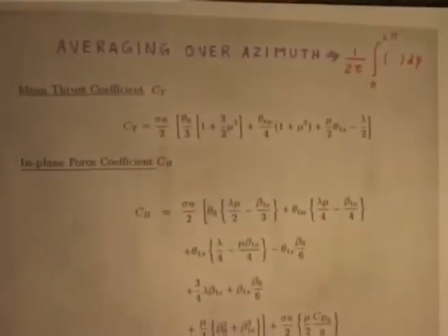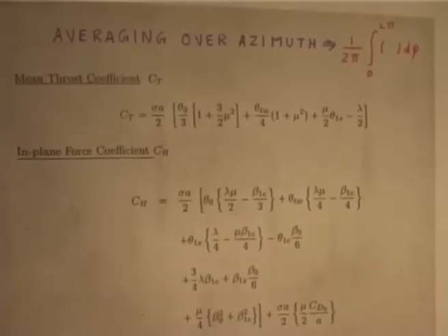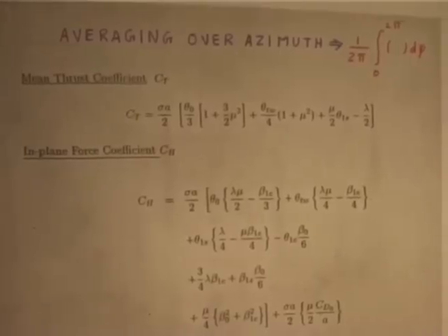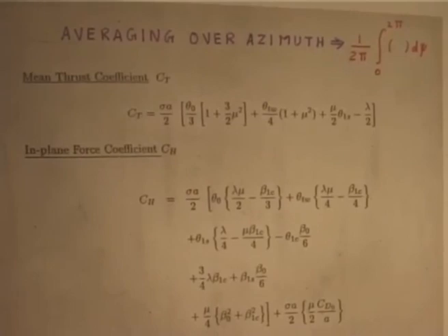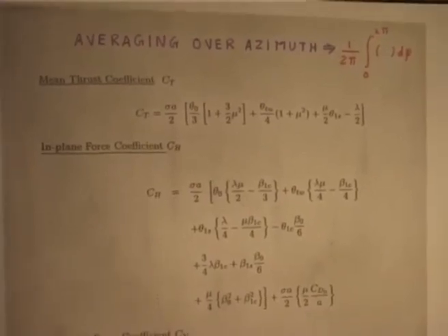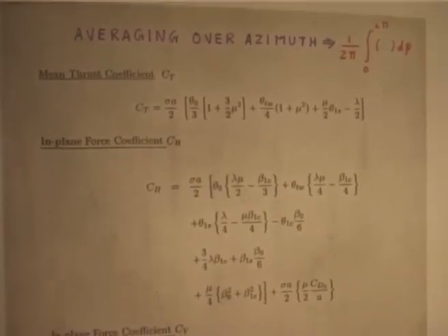Now, since these are all functions of time, I have integrated, substituted theta naught, 1c, 1s, because please remember all these loads vary every instant. It is not that they are fixed; your thrust force is varying, side force is varying, longitudinal force, torque, moment, all these quantities are changing every instant.